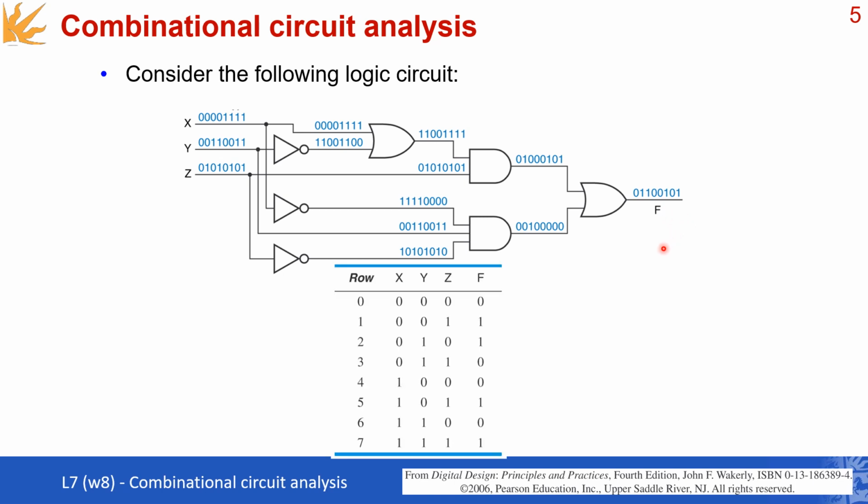So it's that easy. After you do this process, you have all of the rows. Each row over here is like vertically reading the inputs. Like if I randomly pick the sixth row, which is row 5, the input should be the number 5, of course. It's the one over here. And if you go over here, you will realize that the output should be 1. So that is a very easy way to approach a logic circuit and extract the truth table.